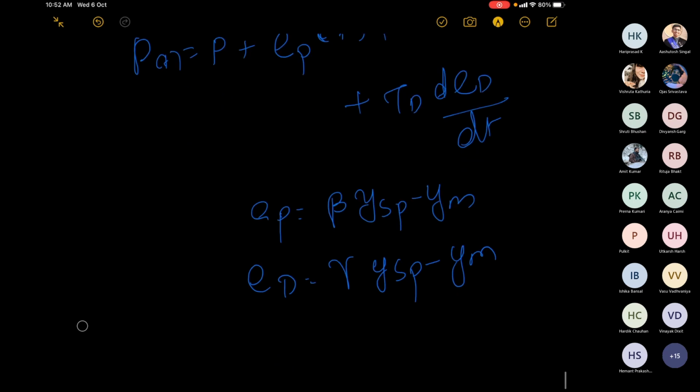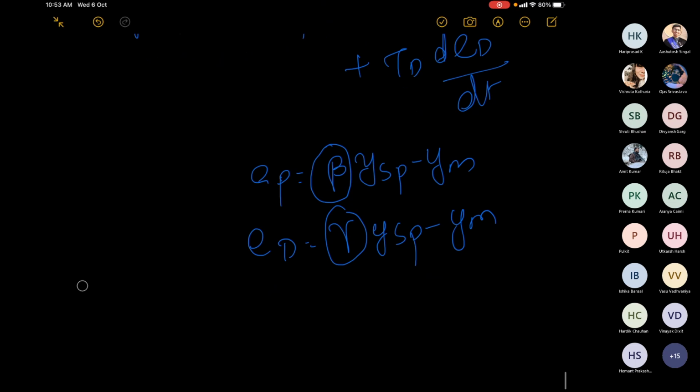So there are multiple options now. If you put 1, you will get your original formulation back. If you put 0, you would completely eliminate the derivative kick. But you can also do what you call a smooth change of profile. For instance, instead of keeping this beta as a constant, you would vary it between 0 and 1 over time.